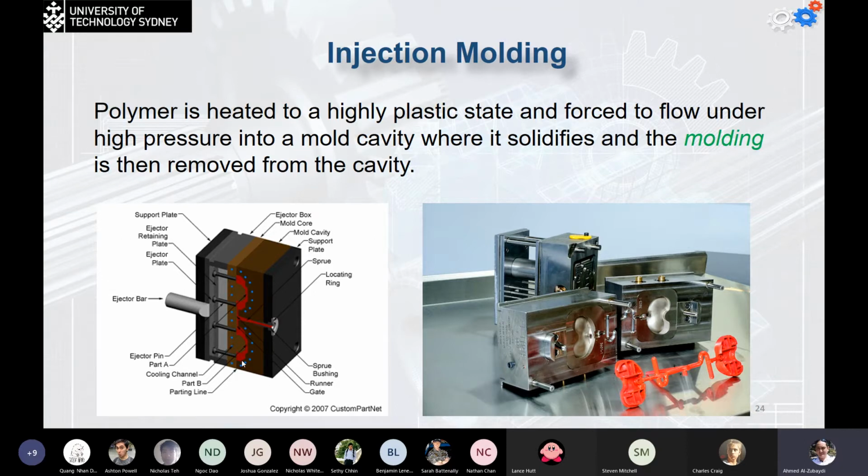I think the typical timing for the solidification is something between 10 seconds for the small parts, and maybe it can go to 30 or 45 seconds for the bigger parts. But of course, if we make something like a thick wall, maybe it's going to take even 1 minute or even 5 minutes to cool down. The mold usually contains multiple cavities, so I'm not going to make one part each time I inject the plastic. I can make multiple moldings for each cycle.